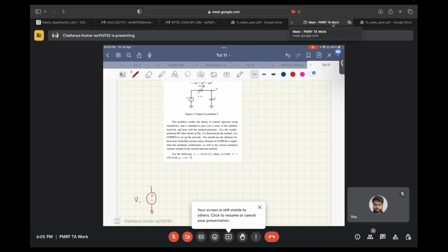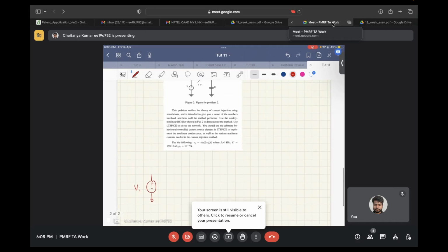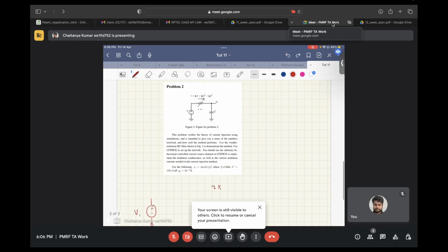In LTspice, you can plot the spectrum. Here, what will happen due to these nonlinear terms? V02 basically will contain the DC part and the second, 2 kilohertz tone, right? So what will we have in V02? It will have a term with Vi square, correct?